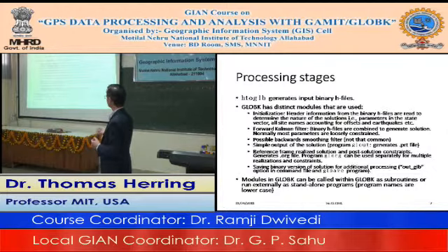There's a simple output, which is a program called GLOut, but again, you don't normally explicitly run it. And it just literally is an output of the solution which you just generated. It generates what we typically name as a .prt file, for print. Sometimes we actually don't bother outputting this at all, just because we'll find that the way we run most of the solutions, what comes out of that is still quite a loose solution.